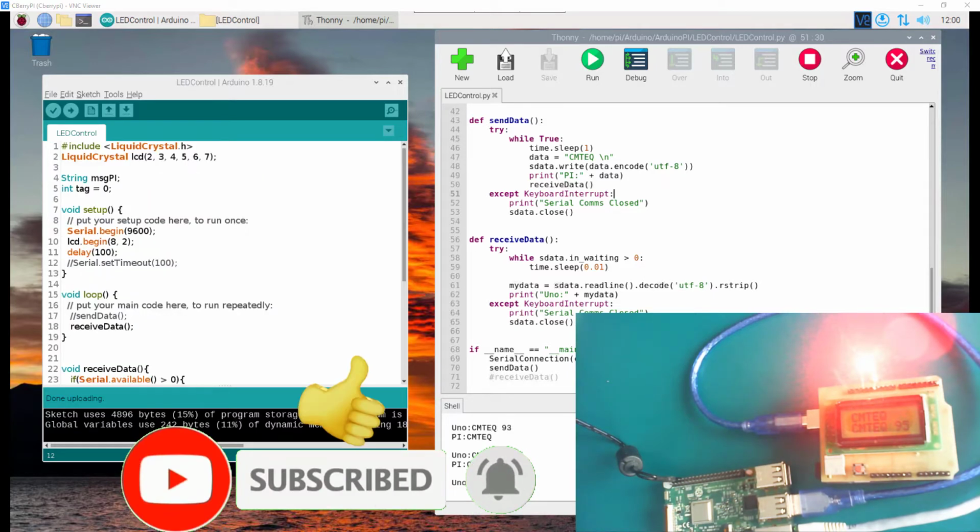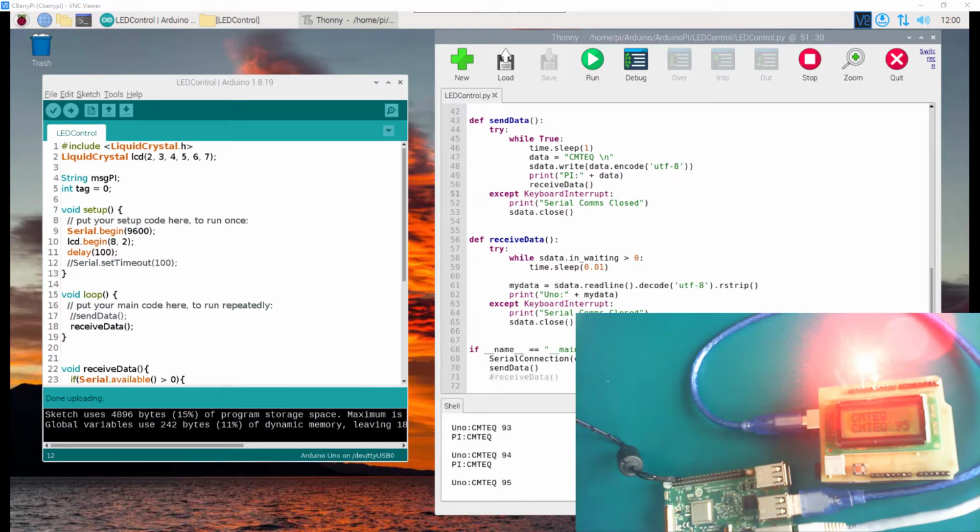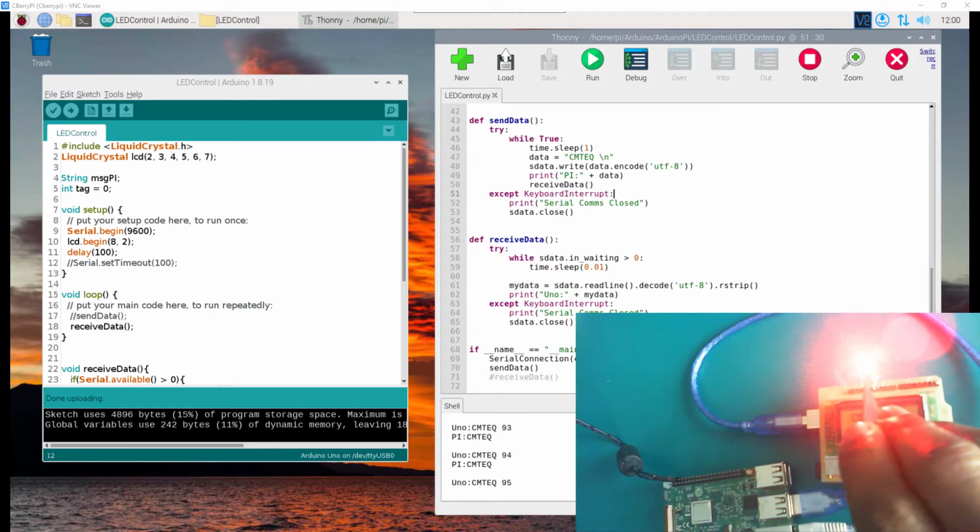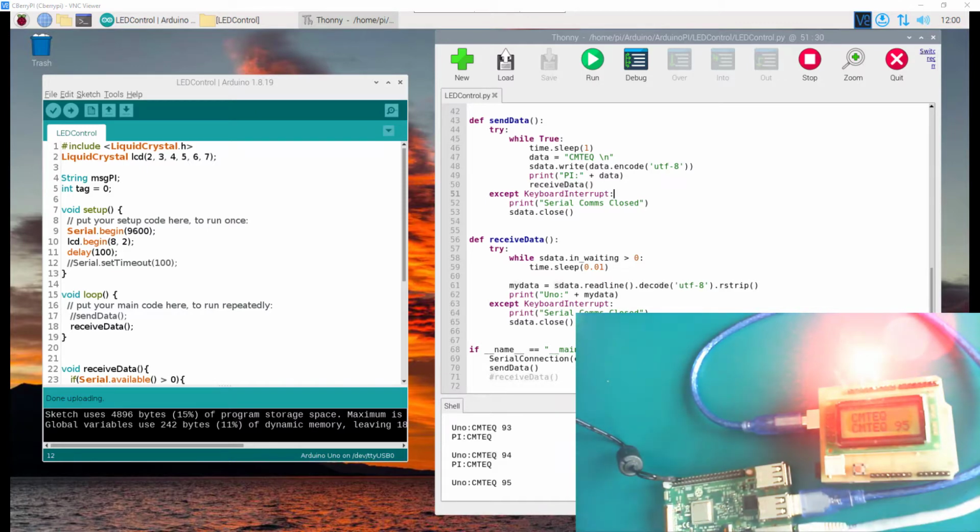All right, so first off, what's the story here? We need to control this LED. This LED is the subject here. So we need to know what the hardware configuration of this LED is. When we look at our Arduino right here, we can see that the LED is attached to pin 8, 9, 10, 11, 12. So that is pin 12, and then it's going down to the ground pin. So that's our LED configuration.